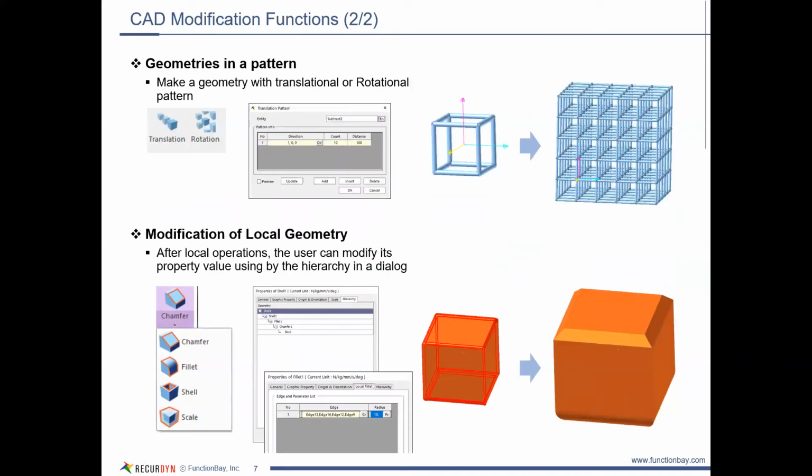Okay, next geometry related enhancement is to be able to do a pattern of geometries or a pattern of solids. So you can see here we have a solid that's this collection of tubes hooked together, so it's just a box with kind of just the edges. And then by using the pattern command, we were able to come up with the complex geometry shown on the right.